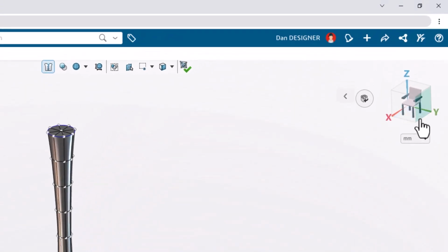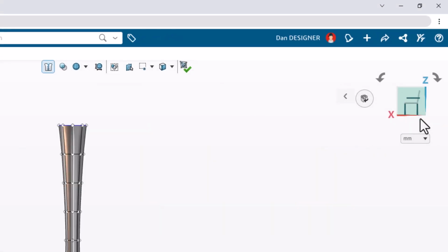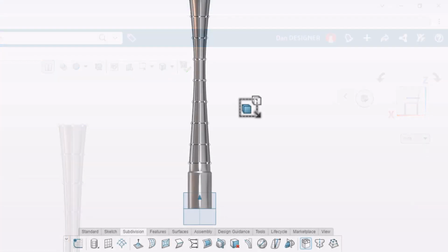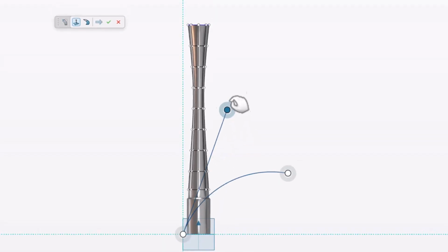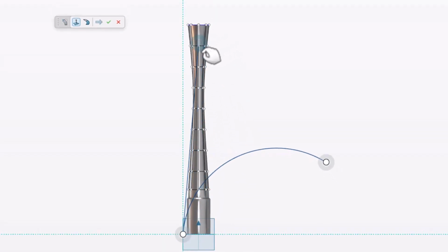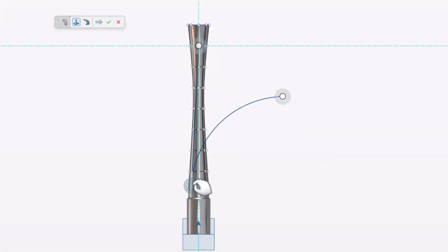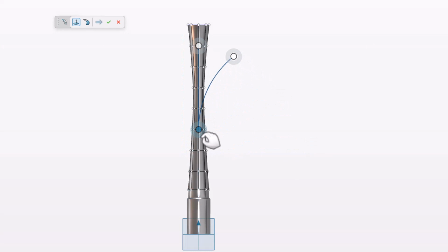Now it's time to bend this faucet into shape from the side view, specifically the ZX direction as shown in the orientation triad. Let's launch the Arc Bend command from the action bar. The Arc Bend tool includes an arc and a bend line that we can adjust. Click and drag the ring of the endpoints to position the line like shown.